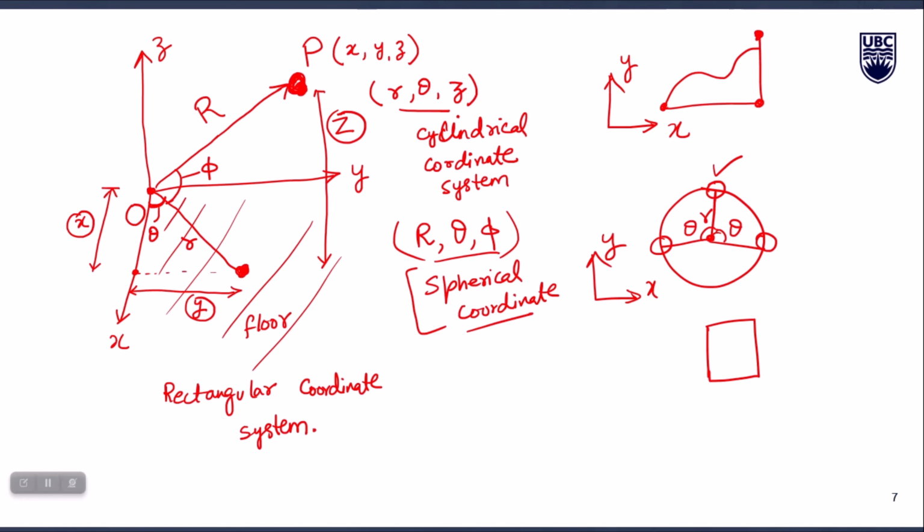So if a building is a rectangular shape and all the components are either parallel to or perpendicular to that main or minor direction, a rectangular xy axis will obviously be more convenient to define the location of, for example, corner points of a building or any object within that plan, because it will be either aligning in this direction or aligning in this direction, right? A wall will always be aligning towards the main side or minor side.